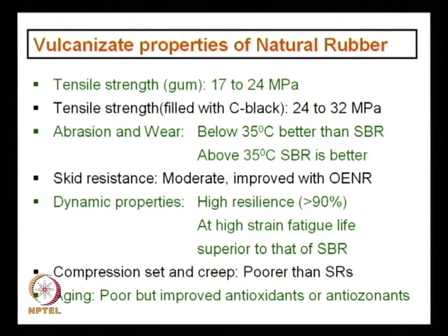Stress your load, applied load, then after application it is released. So, continuously it is application and release, application and release. So, this kind of cyclic load is there. So, this is called dynamic stressing, and that is actually evaluated in the laboratory in simulated condition by a flexing machine or fatigue to failure machine.